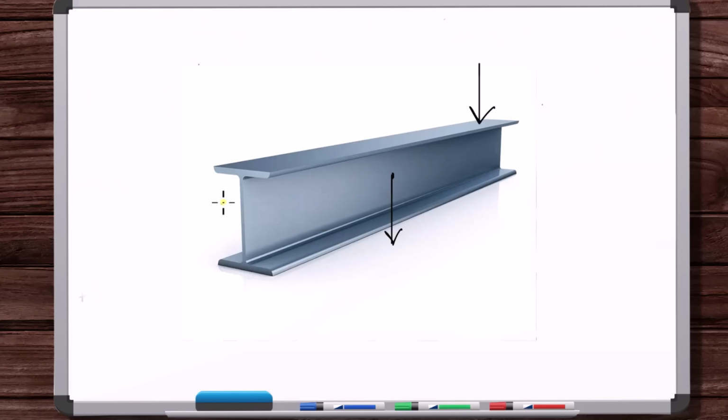Okay, so again, somewhere on this surface, if you got the volume under the pressure distribution curve, you have a resultant force preventing translation in this direction, preventing translation in this direction, and then a resultant couple moment, not moment, couple moment, preventing rotation about this axis.